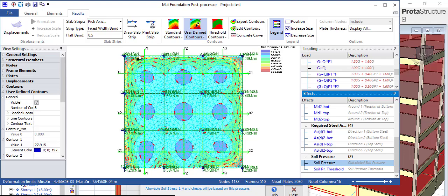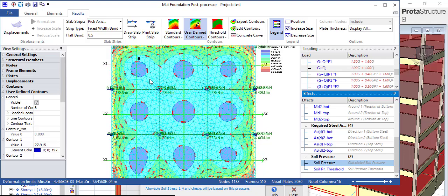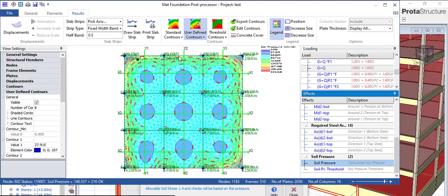But normally what I do if I want to do a raft, if you look at the slab width and length, you find that it's 5 meters by 5 meters, which is quite big. So what I do normally is to break the span. If you break the span, it will reduce all this challenge you are getting. So that's the second way you can do that. Another way is to create an apron. So I think I'll stop here.